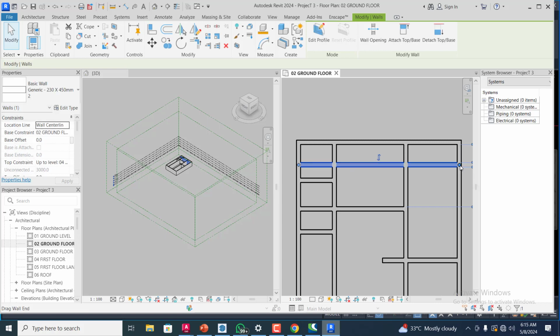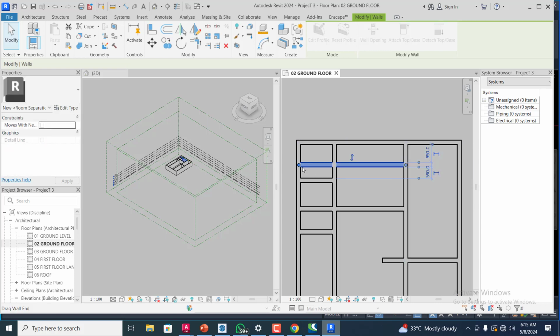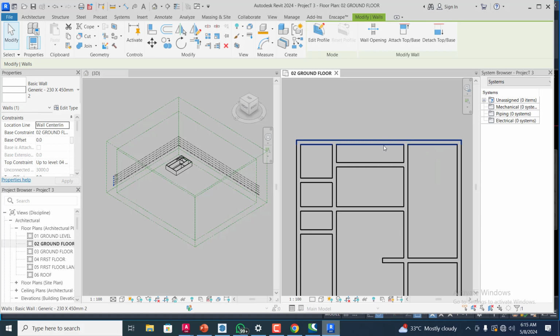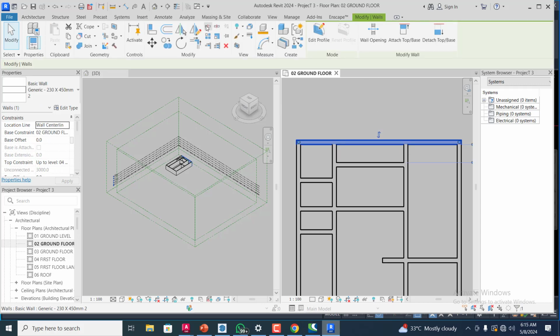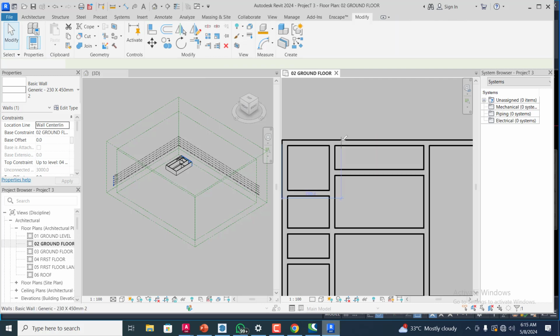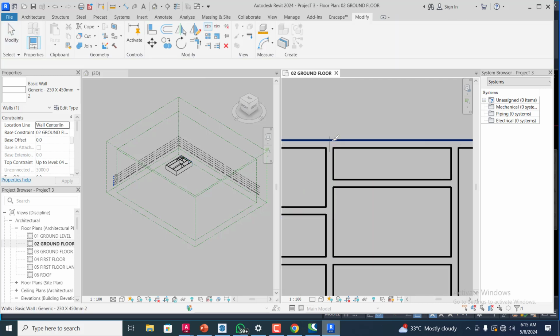So this is going to be like this. This will be like this. And then as for this, I can break this. Let me click this wall. Click on split elements. I know you can remember this too as well. I can split this. At this, split this. So it has been split. So I can just simply delete this.